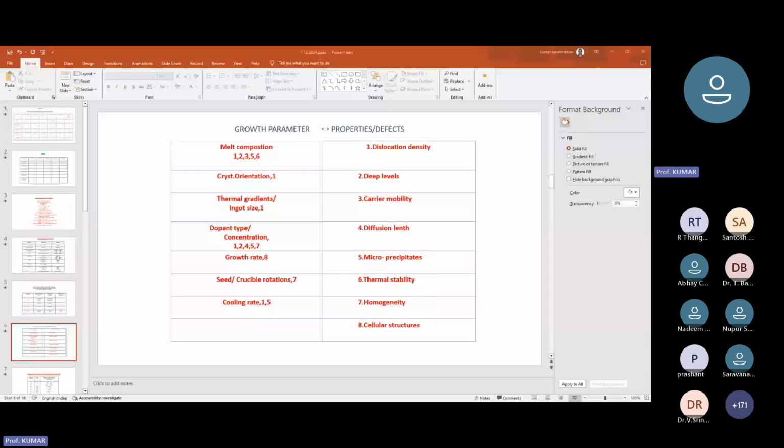because there are conditions of heat transfer, and the heat transfer can happen through radiation, convection, and mainly through conduction. So that is the reason why we need a good thermal conductivity for the material we want to crystallize. It should have a low vapor pressure so that the material doesn't have variations in the so-called stoichiometry or the composition. It should have a low viscosity, because if it is too viscous, it will be very difficult to grow it as a single crystal.